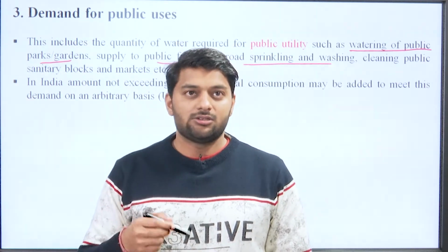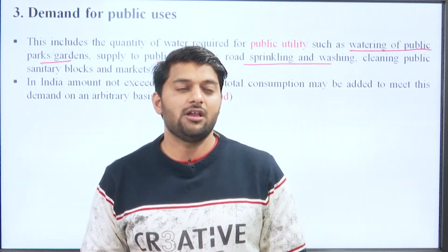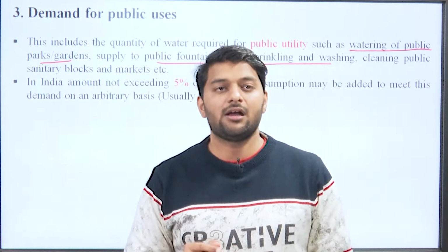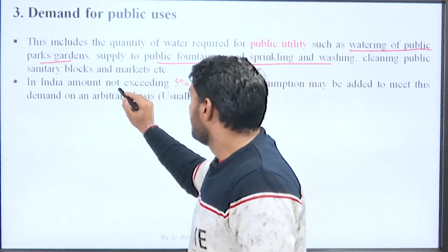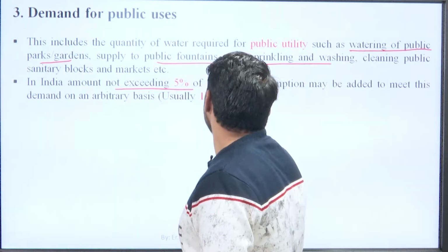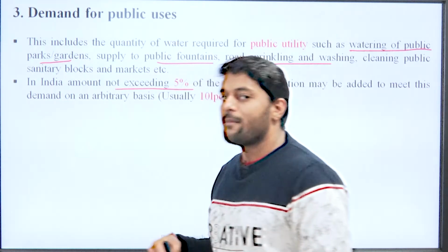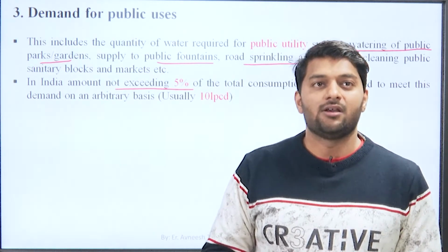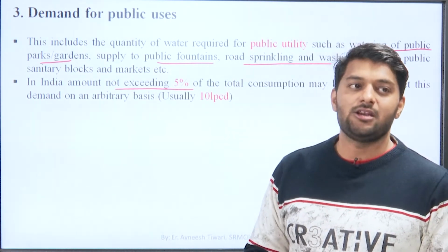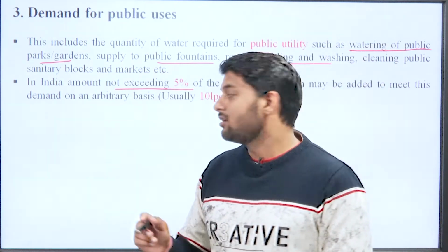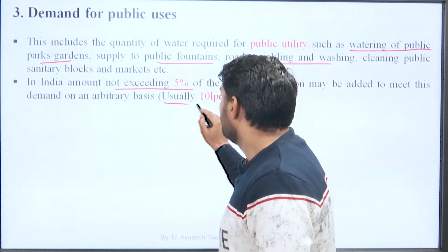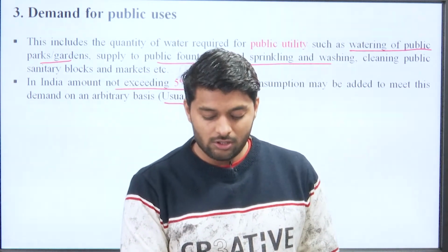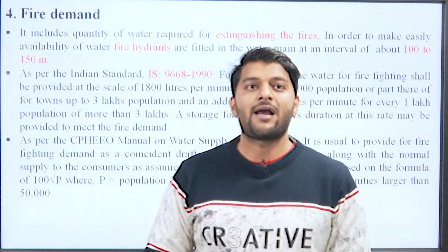So in this demand we are going to cover these particular things. And in India, the amount not exceeding 5% of the total consumption, means 5% of our total consumption, we provide as demand for public uses, and that value is usually 10 liters per capita per day. Okay, so the next one is fire demand.